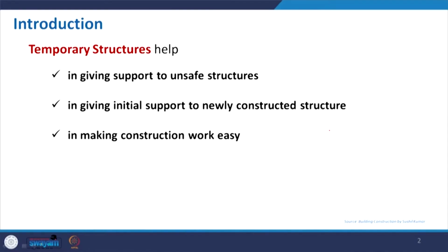Second, it gives initial support to newly constructed structures. Here it basically refers to the formwork. When we make construction with concrete, we mix the cement, sand, stone chip and water to prepare the concrete. It will be in a semi-liquid form and will not be able to take the load.